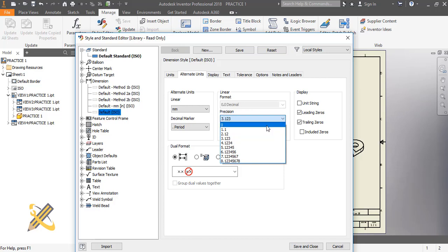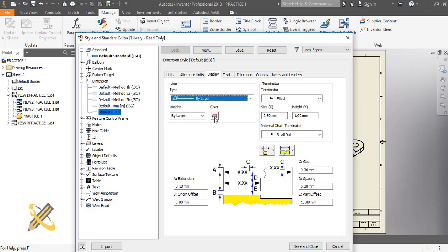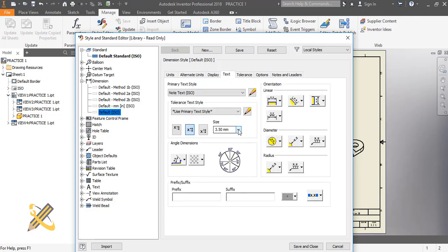Move to display. So my offset standard technical drawing should be 2 mm. Yeah, the offset. So my arrowhead, this one should be 3 here. Alright. Size to be, let's say, 4 mm. Alright. So for this to be aligned,